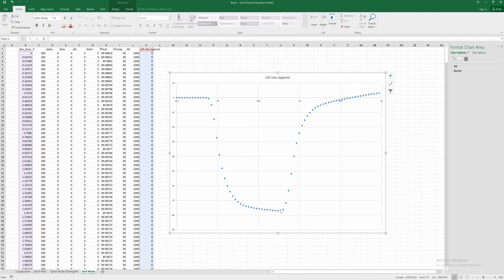And then I moved it back. So that's what this step change is here. Then I let it go back to 0. And again, we came back and asymptotically approached a constant roll rate here. So it's a very convergent mode, extremely highly damped, very much over damped. We're not going to get any oscillation in here.